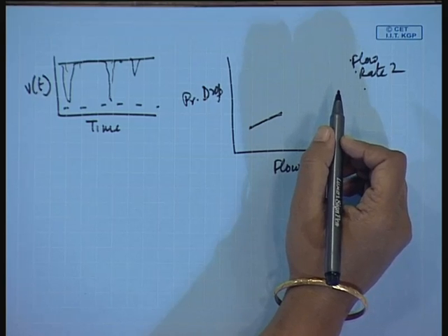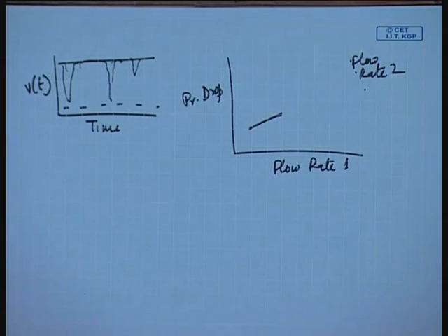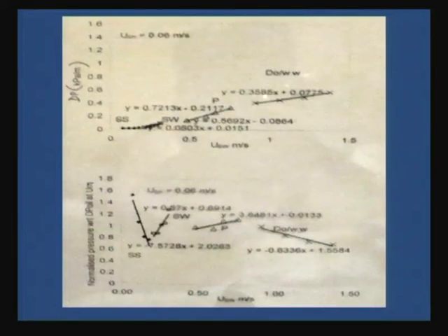Okay, for example, I have got one such example. If you observe this particular slide, you will find that we have obtained different slopes for different flow patterns. This is for stratified smooth, and this was for liquid flows that we have got. In liquid flows, we could not use the conductivity probe technique. Why? Liquid was sticking to it, and then a lot of problems were there.